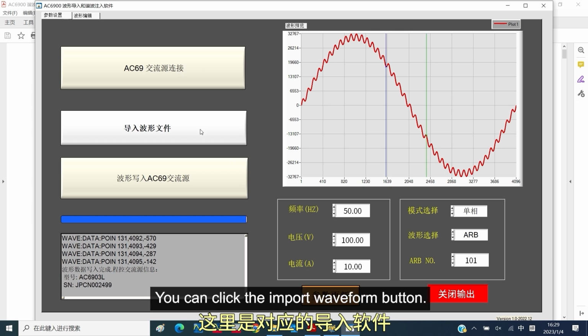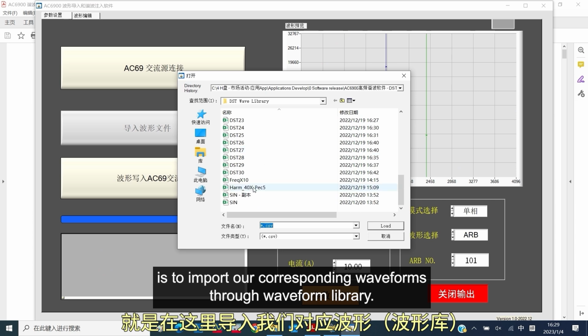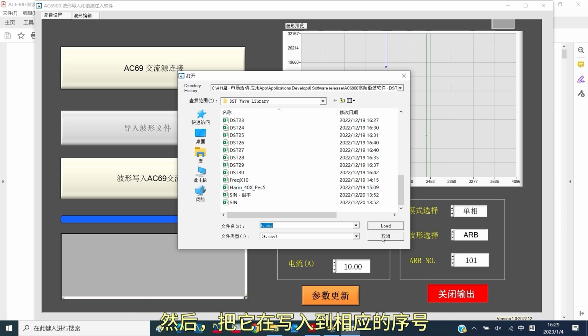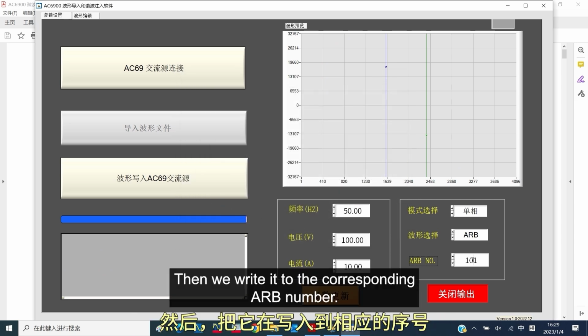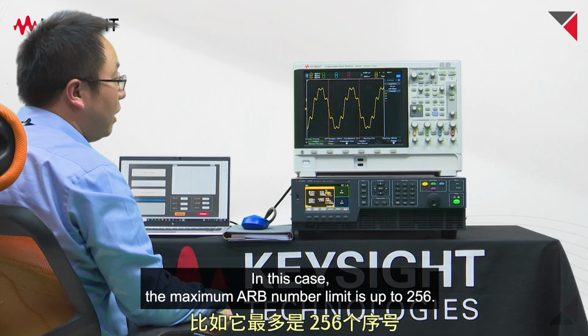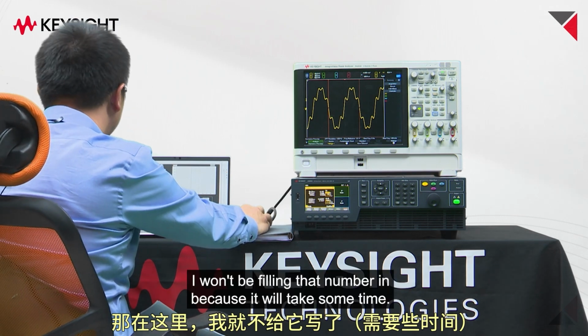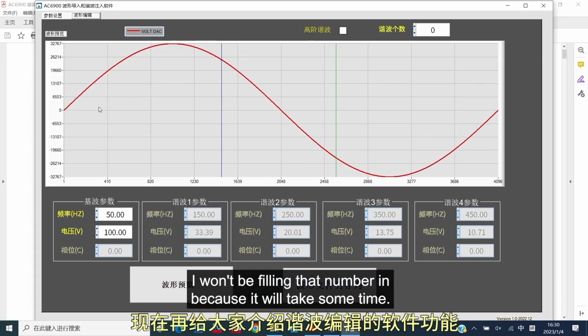You can click the Import Waveform button. Now what we need to do here is to import our corresponding waveform through the Waveform library. Then we write it to the corresponding ARB number. In this case, the maximum ARB number limit is up to 256. You can fill that number in. But for this demo, I won't be filling that number in because it will take some time.